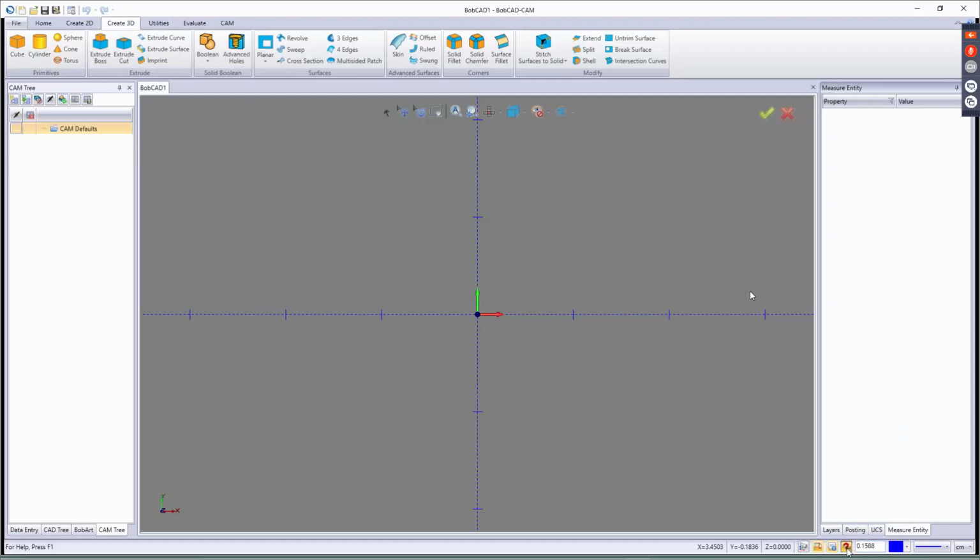We've got our magnet here if you want to use that. That's our snap increments. So if you're drawing a straight line or something, it's going to snap. In this case, it's in centimeters now, 0.1588, so it'll snap every 0.1588 along the way. Same thing with circles. And then I just disabled that. You can enable and disable flyouts. We'll get into those later.